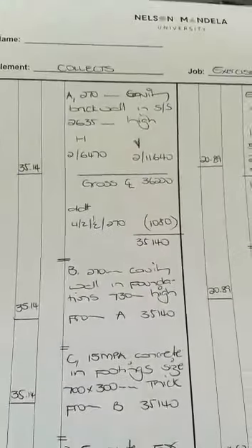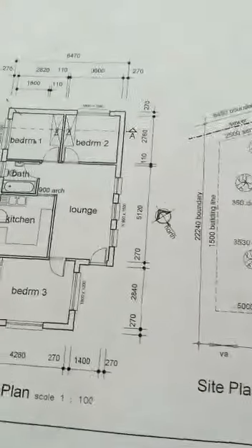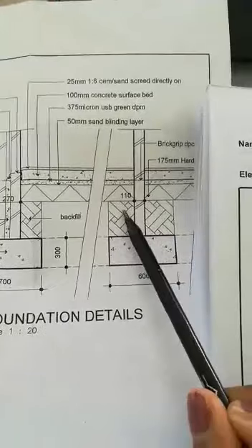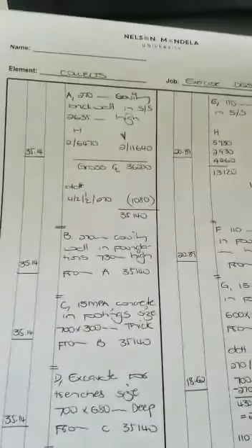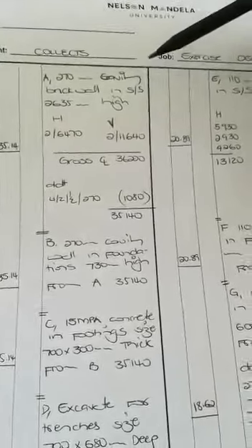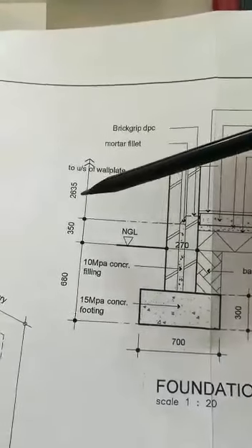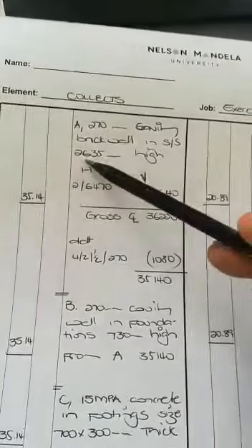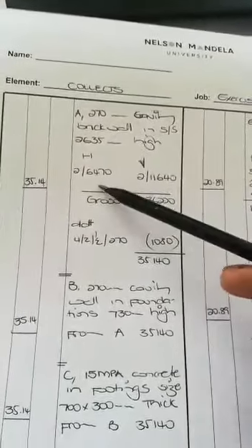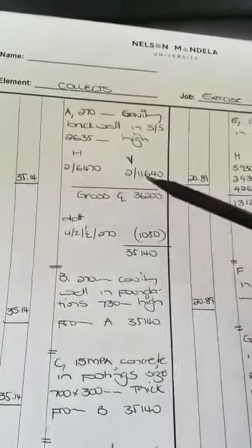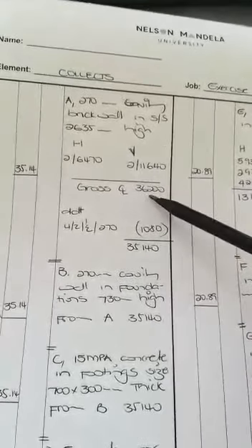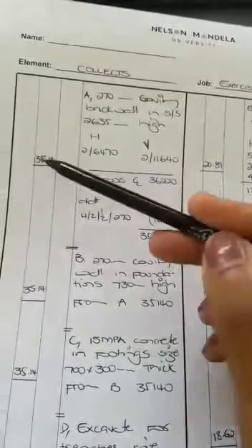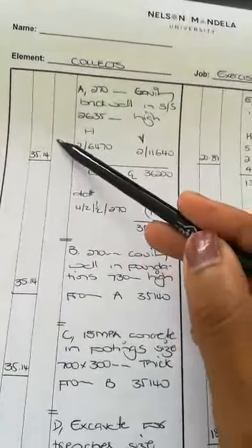Okay, so let's start with our collects. We can see from our drawing here and our section that we've got a 270 and we've got a 110 brick wall. So we are going to start with our 270 cavity wall in superstructure. And we've been given over here that our superstructure dimension is 2635, so we have it as 2635 millimeters high. And then we get our dimensions for the horizontal multiplied by 2, the vertical multiplied by 2. We get a cross center line, where we do our deducts for the corners. And then we get our center line, which we then transfer to our dimensions column.